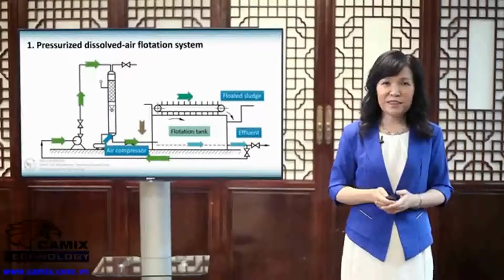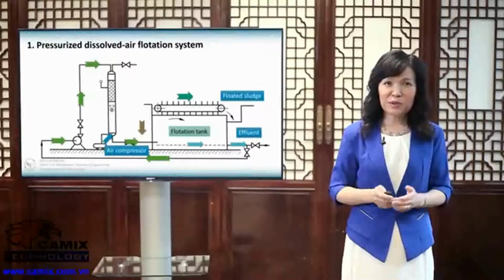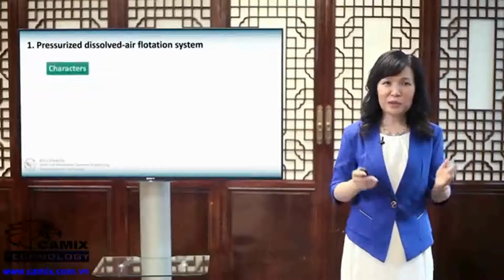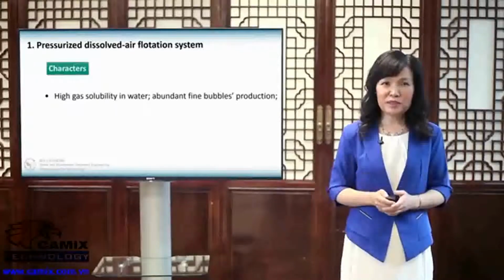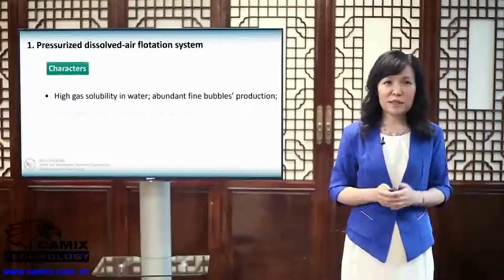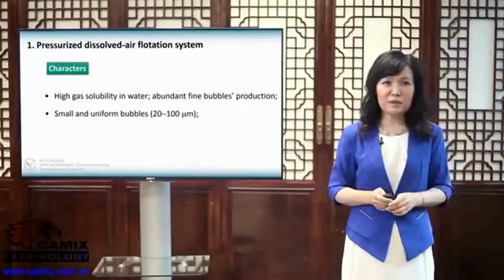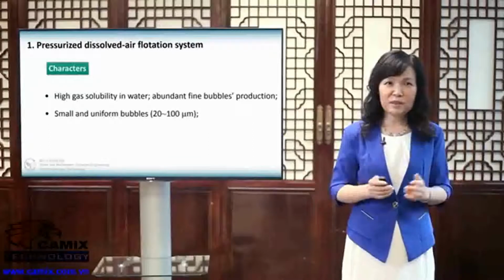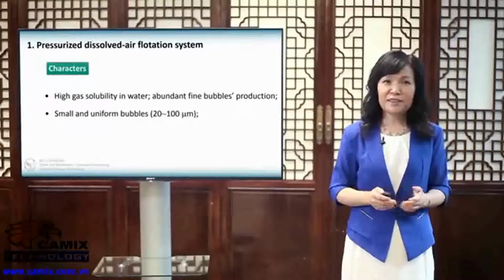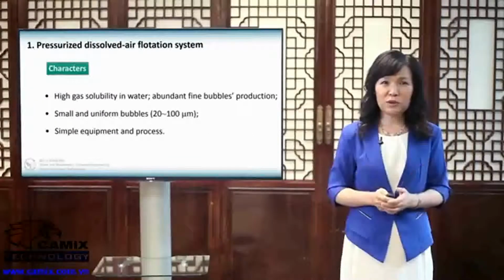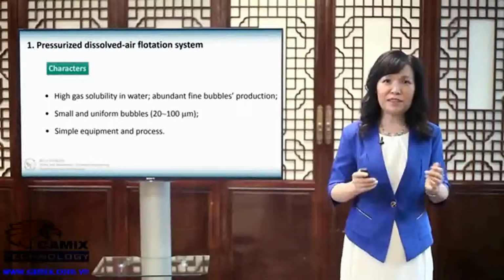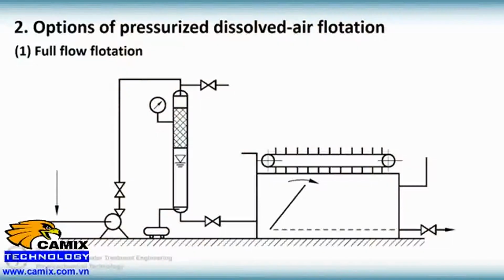Pressurized DAF can obtain a high solubility of air in water. It can supply sufficient fine bubbles with diameter ranging from 20 to 100 micrometer and uniform distribution. Besides, equipment and process are simple, so it's the most widely applied flotation process in the field of water and wastewater treatment. Now we are going to introduce a fundamental process of pressurized DAF.